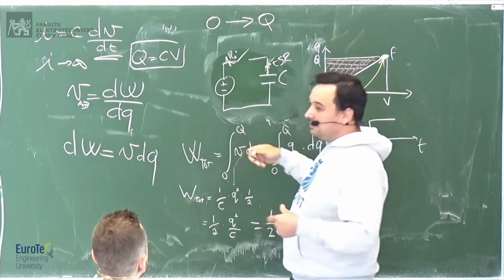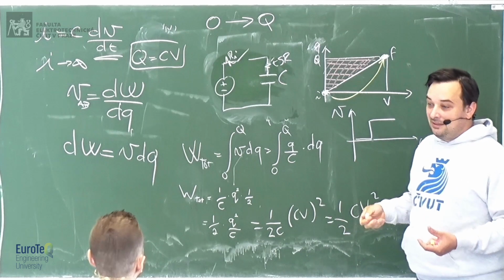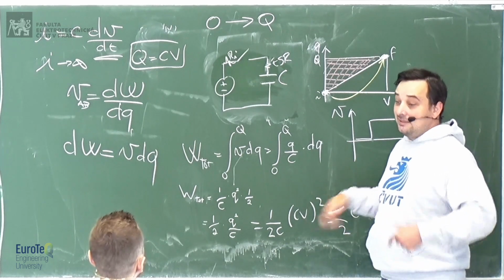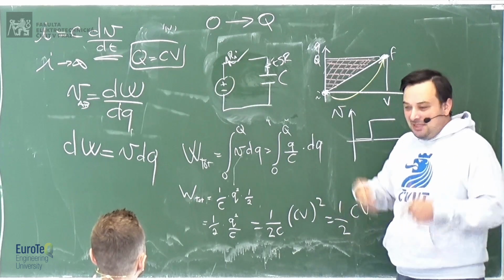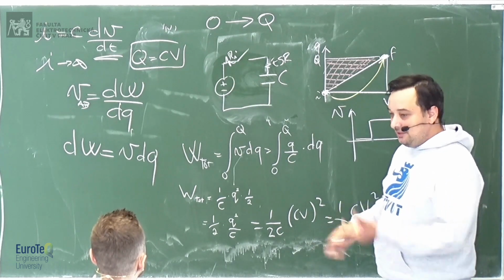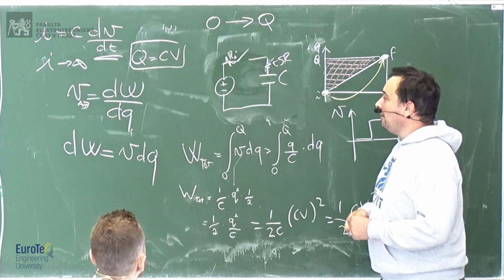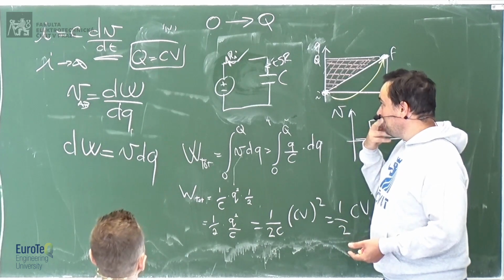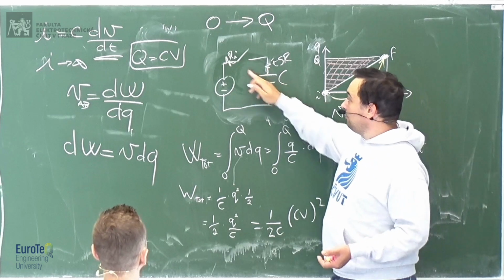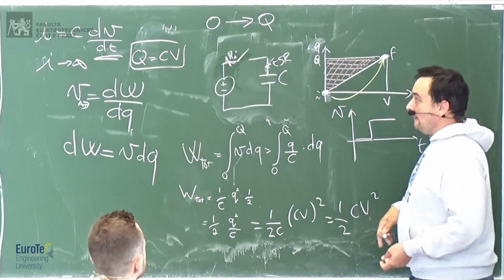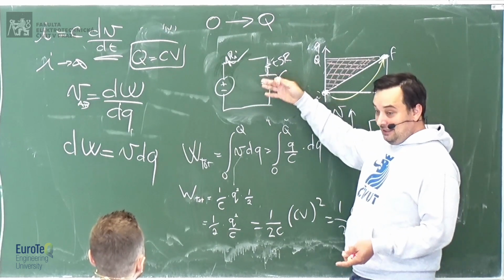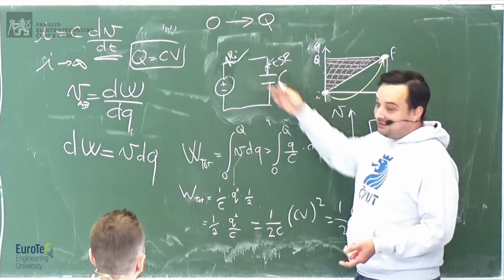Because there is no source of voltage which can provide infinite current. There is always some limit to the current that it can provide, so you always have some internal resistance. It might be small, but you always have this resistance. So, of course, in these conditions, the current will be limited by these resistances, which are tiny. But still, it's going to be a large current if these resistances are low.